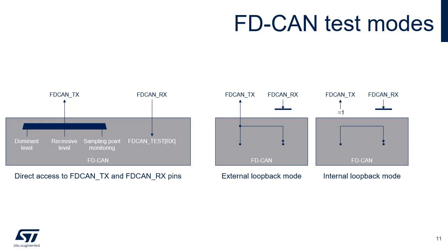In loopback mode, the FDCAN controller is designed to operate independently from external communication. It achieves this by disregarding acknowledgement errors, which occur when a recessive bit is sampled in the acknowledgement slot of either a data or remote frame. This allows the controller to focus solely on internal operations without being influenced by external network conditions or acknowledgement feedback.